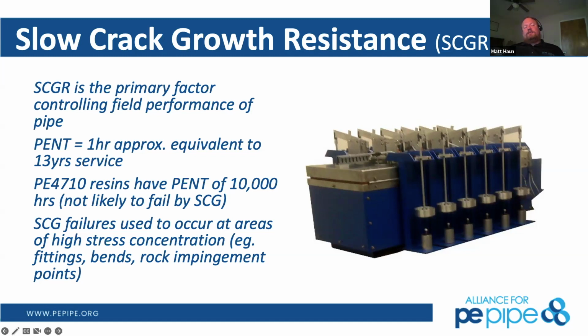Now, that's not to say we don't still have to take care to follow proper installation processes to avoid rock impingement or bends, but from pressure itself, we're not going to see that as a failure mode. You know, Matt, people have given me a hard time for talking about failure, but slow crack growth has been a failure mechanism of polyethylene, and the industry engineered it out of the product.